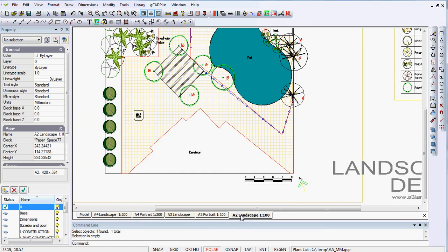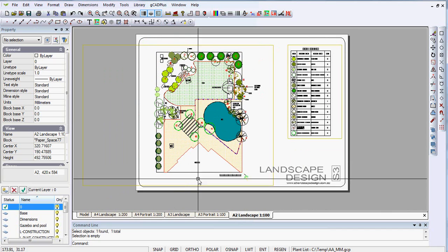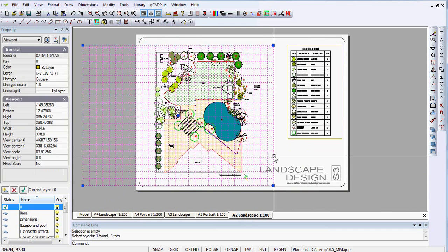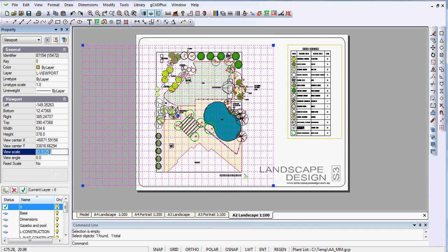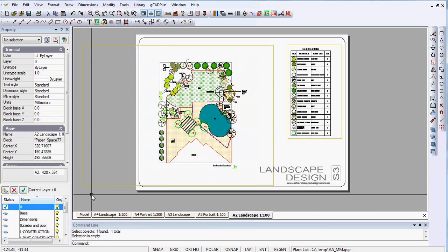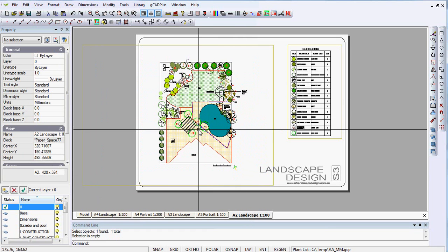Let's return again here. So if I needed a fixed scale and I wanted to put some text in here labelling that view a fixed scale, I would click on the frame and type a value of 100 and set that as a fixed scale. And now it is showing the scale of 1 to 100, and you could label it as such. But of course you do lose a little magnification, and maybe your clients would prefer a larger view in that sheet.